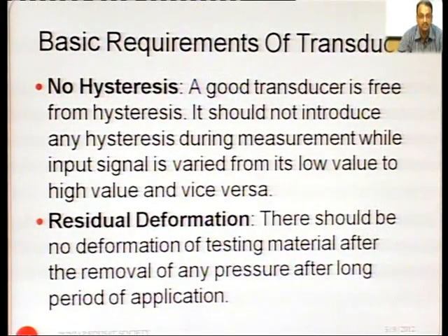No hysteresis. A good transducer is free from hysteresis. It should not introduce any type of hysteresis during measurement while the input is varying from its lowest value to its highest value and vice versa. Next requirement is residual deformation. There should be no deformation of the testing material after the removal of pressure, even after a long period of application.